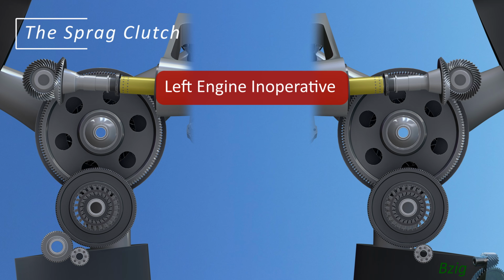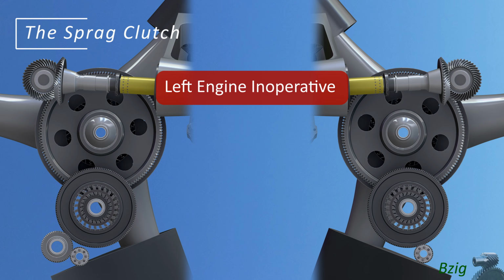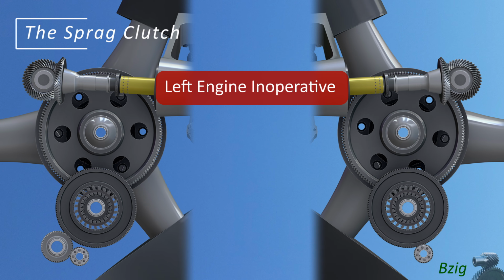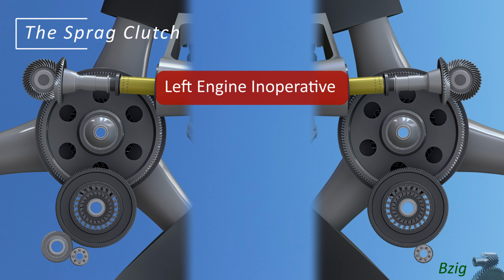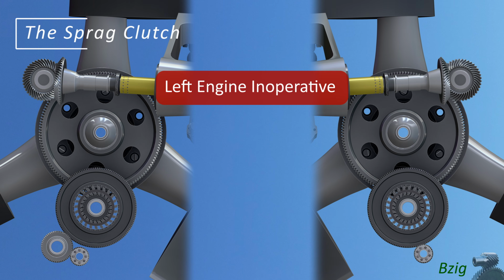Now I'll change the video so the sprags on the left are in the unpowered overrunning position while the sprags on the right are in their normal powered position. The video now represents a one engine inoperative condition with the right engine providing power.